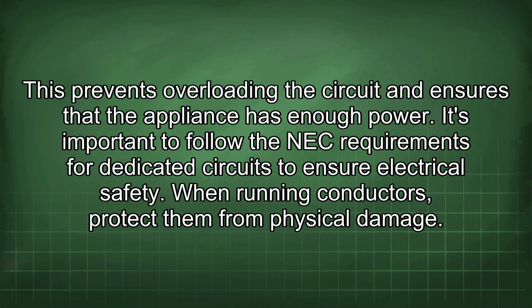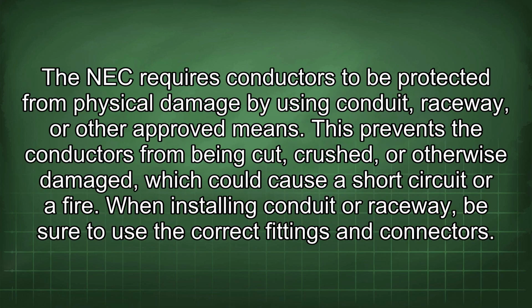When running conductors, protect them from physical damage. The NEC requires conductors to be protected from physical damage by using conduit, raceway, or other approved means. This prevents the conductors from being cut, crushed, or otherwise damaged, which could cause a short circuit or a fire.